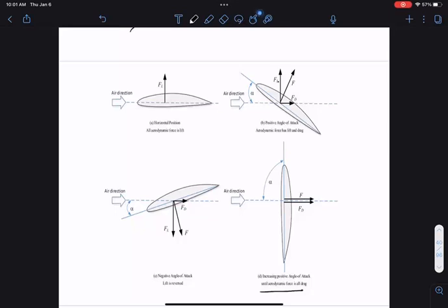Yeah, the last question on this topic. Go ahead. I have one more question. Is there an angle of attack that's low that could reduce the lift force, that could make both forces close to zero, or is that unstable? That's unstable. The force has to go somewhere. There's that much force on the blade. You have something in the wind that hits it, so there's a force. To make lift zero, there's normally some drag. You cannot make both zero. You're a piece of metal in wind, and there's some force on it. Even if you operate very inefficiently, there'll be some force.